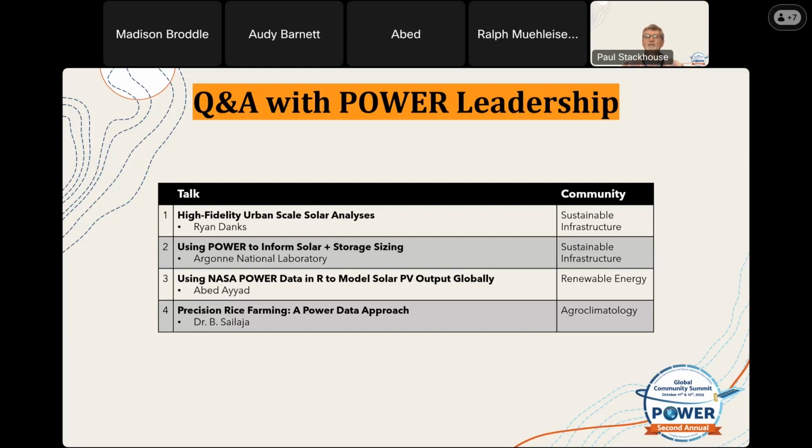It's a hard thing to try to put together an interface for, but for the work and the analysis we do, we're sitting here with Python and Julia in the background, just using the API, and we use it directly from Python. We then feed it into NREL's System Advisor Model. So when we pull the data down, if it's an EPW or TMY file, we're able to pop right into SAM. It's fantastic.